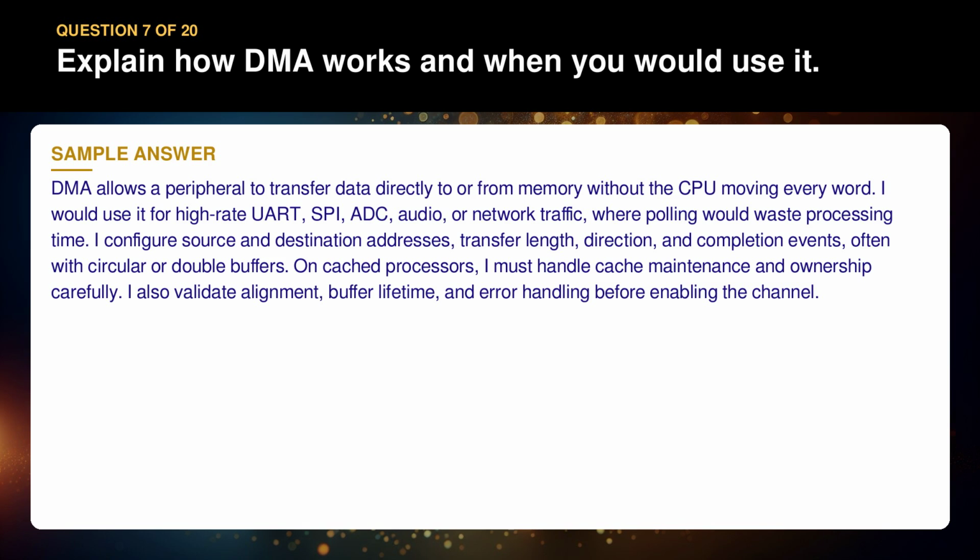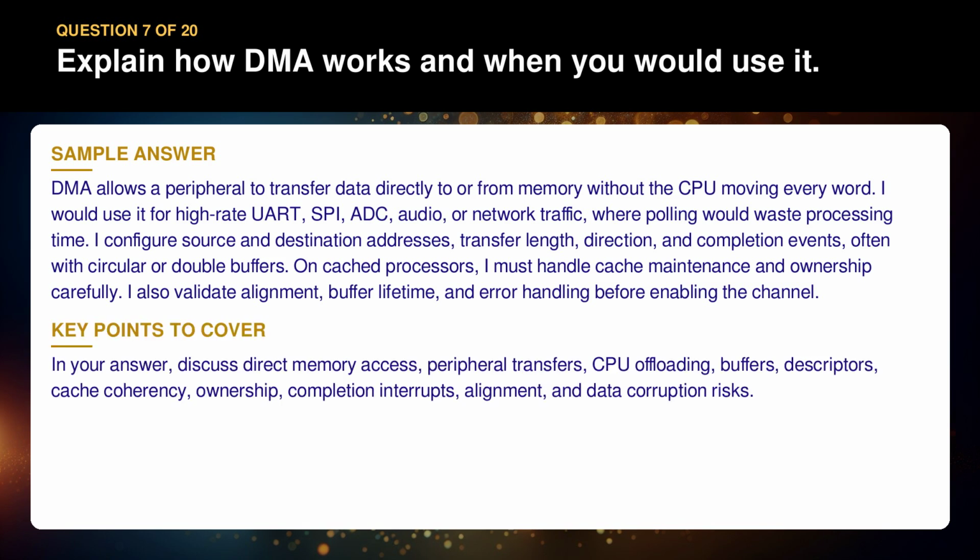On cached processors, I must handle cache maintenance and ownership carefully. I also validate alignment, buffer lifetime, and error handling before enabling the channel. In your answer, discuss direct memory access, peripheral transfers, CPU offloading, buffers, descriptors, cache coherency, ownership, completion interrupts, alignment, and data corruption risks.